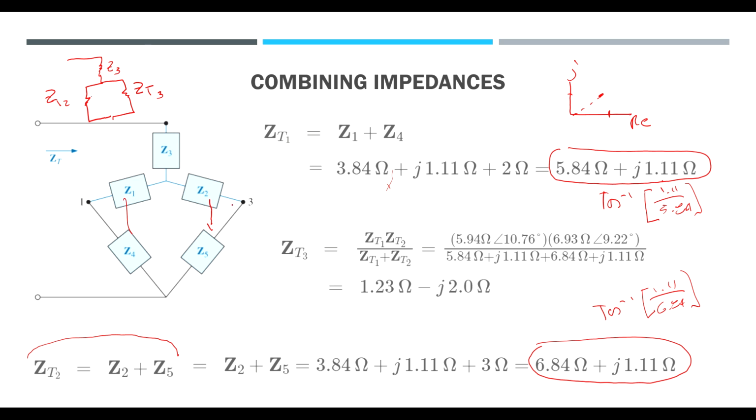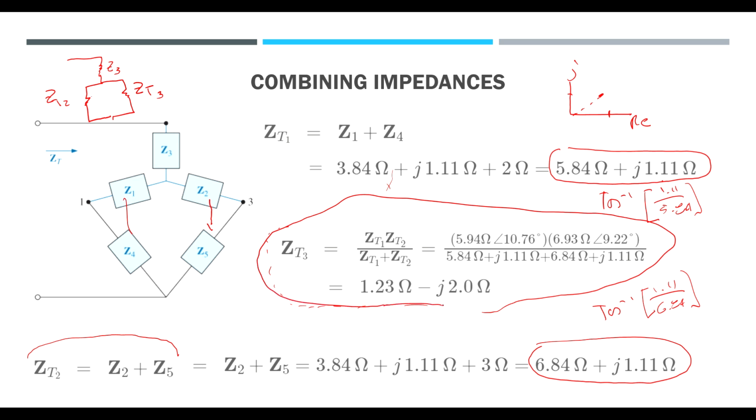So in other words, we compute the parallel resistance between 2 and 3, and we get this value. So that's the way to simplify the circuits, also to compute the total impedance if you need a total impedance value for getting the Ohm's law for current and for voltage going into your system.